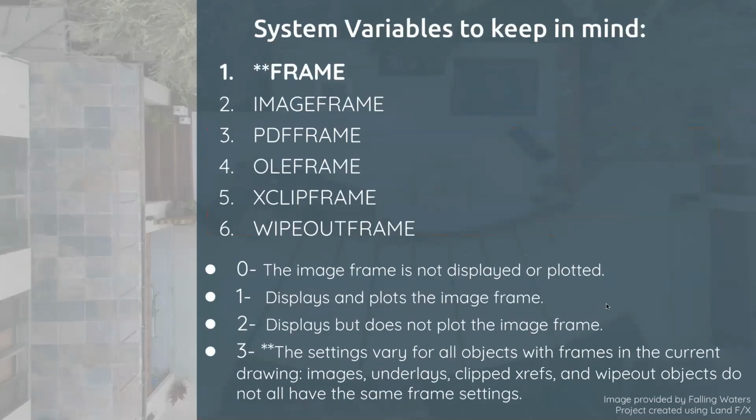Another one to pause on, and just reference here, are some of these system variables. And these really just come down to, as I work with and within CAD, these different PDFs or images, and I'm clipping the image and I'm working with it and I'm plotting this, how I treat those frames of that specific XREF. The settings in the bulleted list below are the values that are allowed for those different system variables.